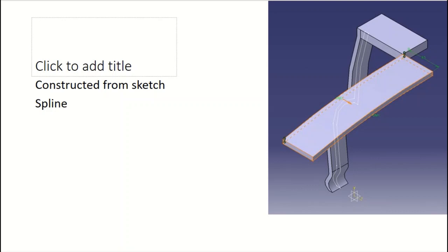So for the car frame, actually, not the front door, I used the door frame of the front door to sketch the B-pillar. And then from then, I created the sloping roof line that connects to the B-pillar as well. This is done from sketch tools with profile and spline.